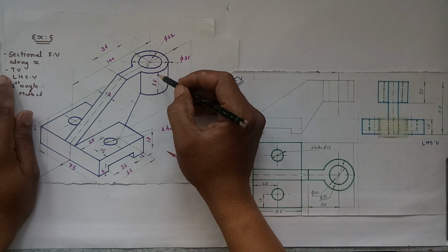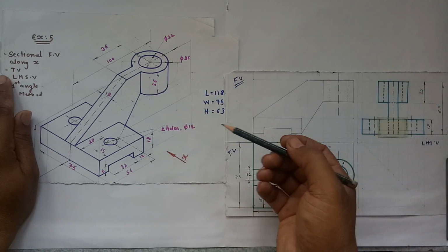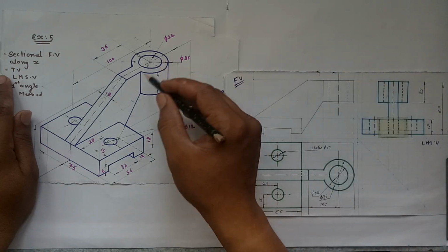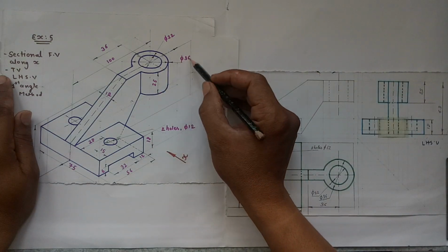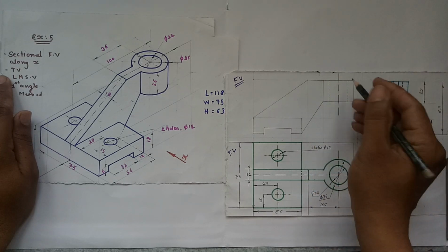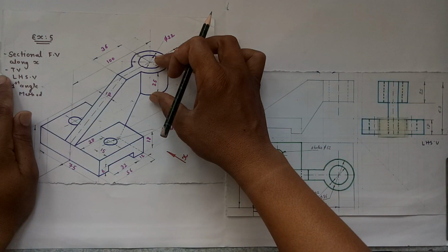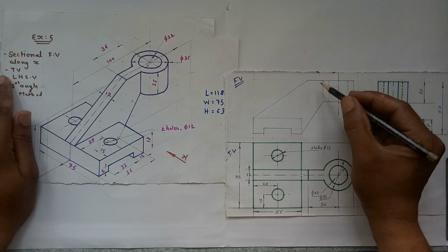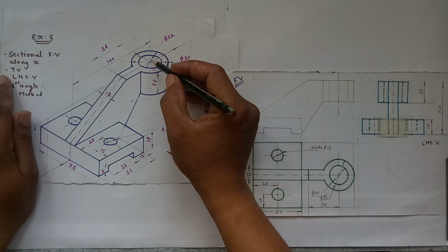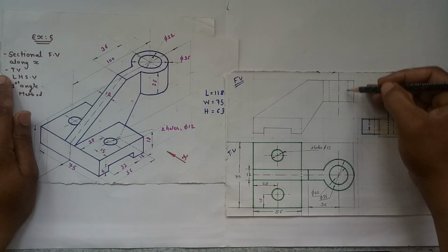Then the cylindrical part is observed as a rectangle in the front view. So we have to draw a rectangle having length 36, projecting this length from the top view and the height from the left hand side view. So this will be the rectangle of the cylindrical part. The circle is going to be hidden in the front view. Project the circle from the top view.